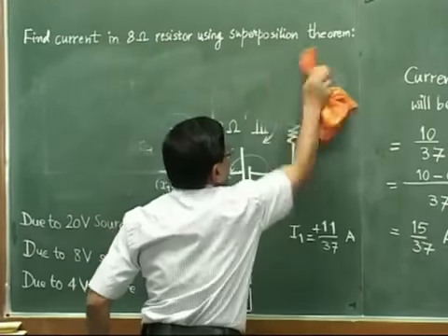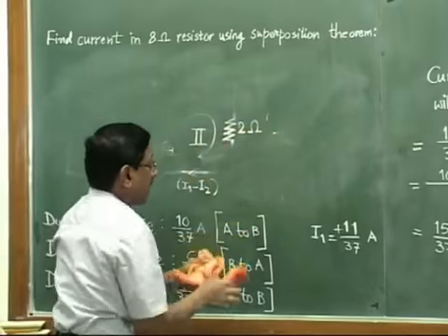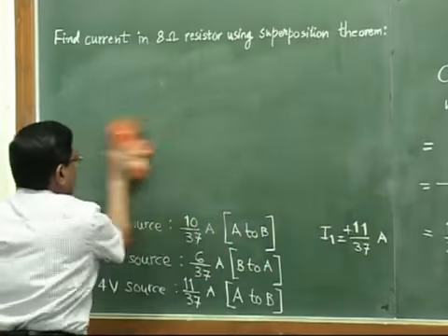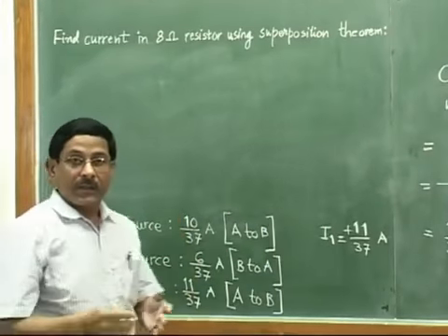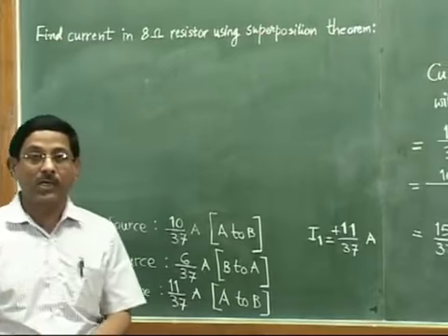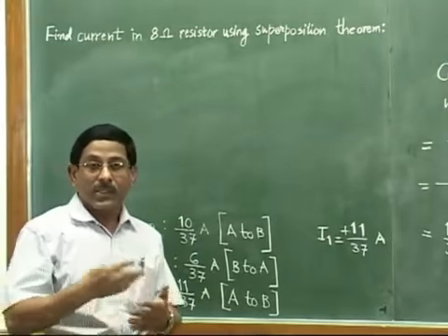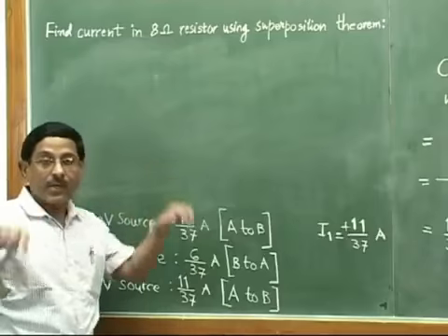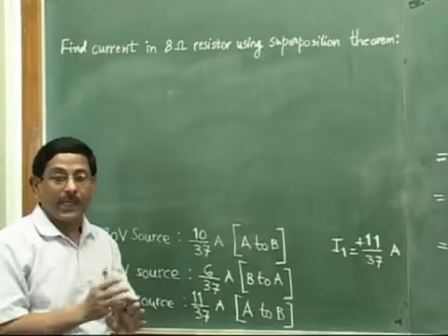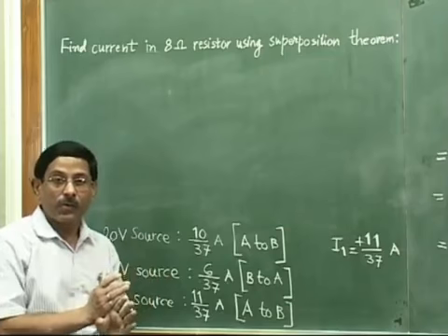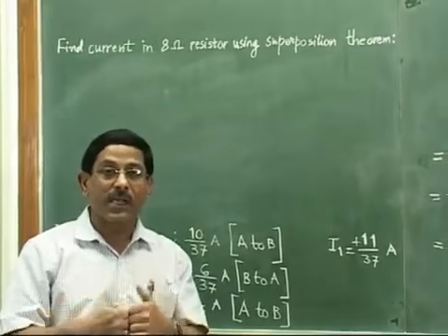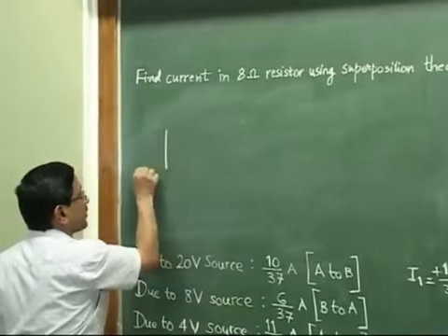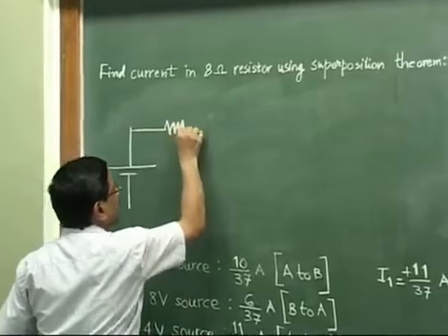Tips for making your time shorter and shorter for arriving at the solution. Okay. So you have to take full benefit of the techniques that we have learned: series parallel conversions or star delta conversions, and other things which are helpful in reducing the networks. You can take a big help of those particular techniques and you have to try. After you start every step, you have to first see whether we can reduce the circuit and then do the current distribution. For example, when it was only first battery acting, okay, this was the circuit that I will draw fast.